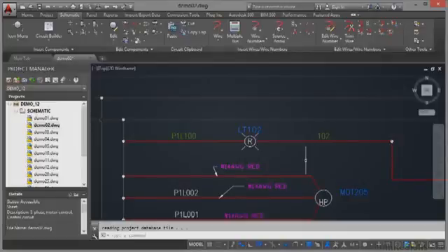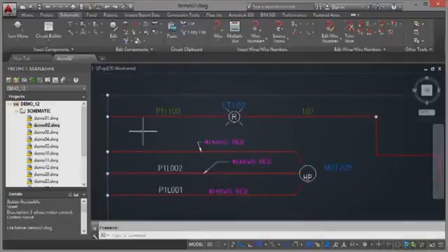Annotating and editing existing symbols that you've already brought into your AutoCAD electrical drawings is very, very easy. We've got Project Demo 12 and we're still in the drawing demo02.dwg. And you'll recognize the pilot light that we brought in earlier. Now, it's very obvious to see it's a pilot light because it's got the pilot light symbol. It's got LT102, LT meaning light. The R in the center indicates that it's a red pilot light.